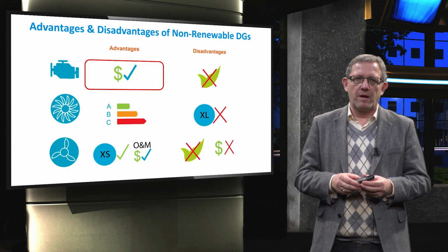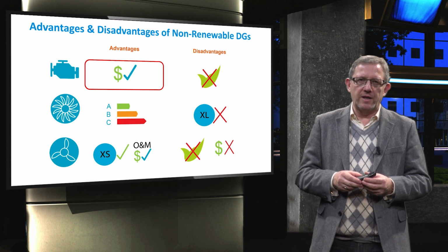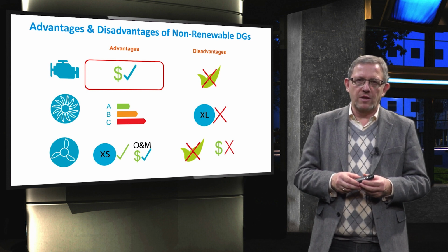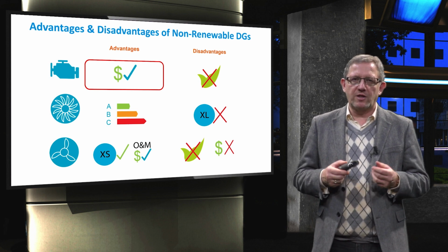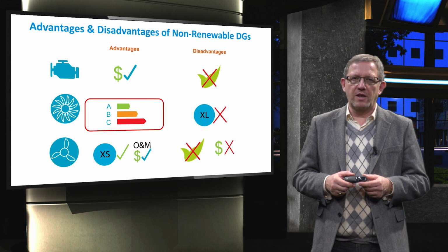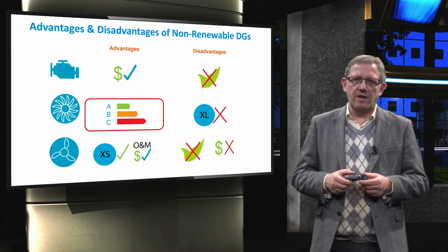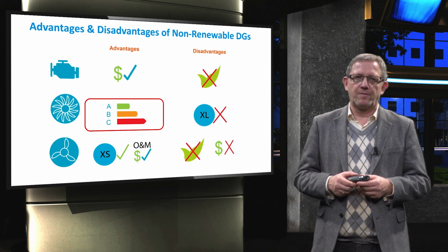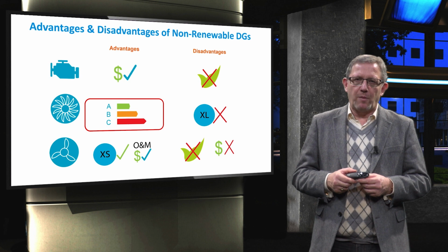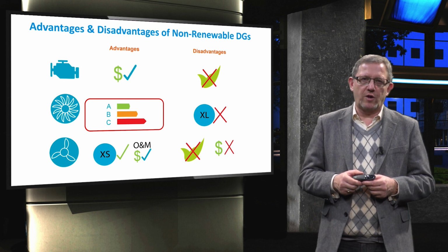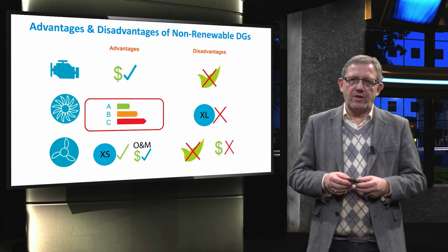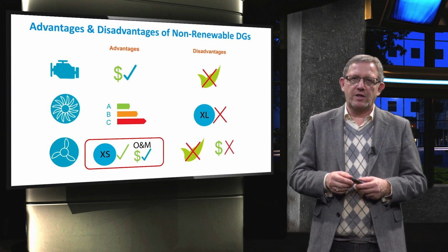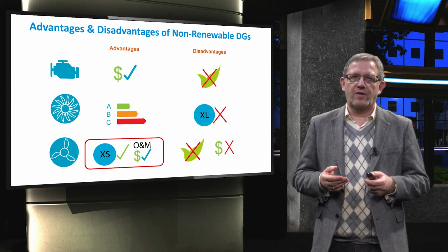efficiency. The advantages of the reciprocating engine are the low cost and flexible control over the input mechanical power. The advantage of the gas turbine is that, as mentioned, they could reach high efficiencies in combined heat and power applications and become more cost efficient. They have higher ramp-up capabilities, which makes them crucial for black start application and covering the peak load. If gas is used as the primary source, then they become environmentally friendly.